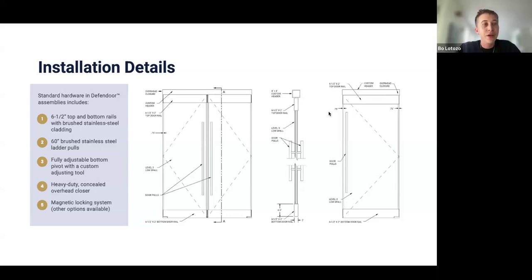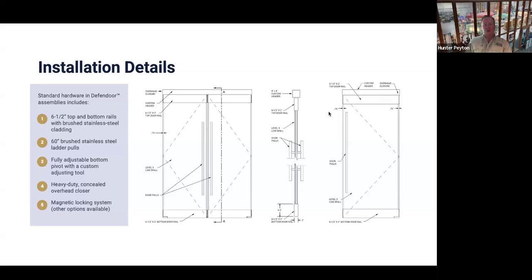That has to be done after the fact. All right, what is the fire rating? We don't have a fire rating on this door. The fire rated ballistic glass is typically very thick and very heavy, and it's just not something we get asked very often. There's always the push-pull between the security need and what the fire marshal wants, and so it just really depends on what is the most crucial aspect for the client.